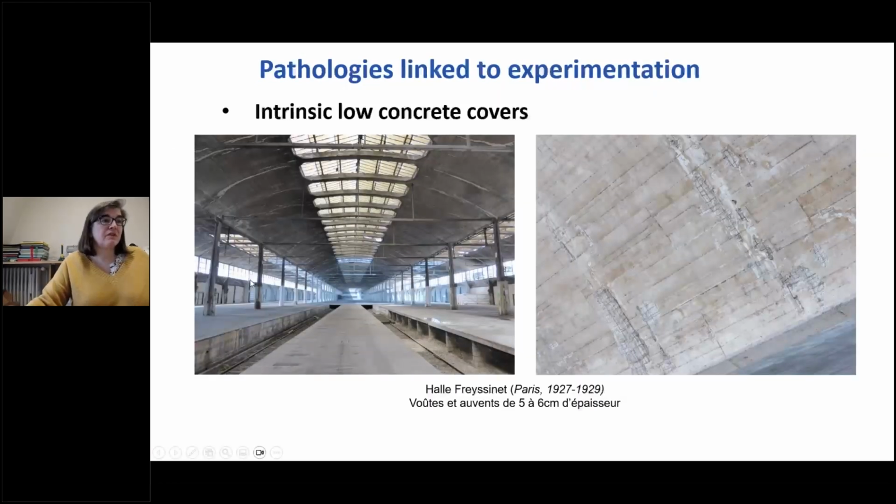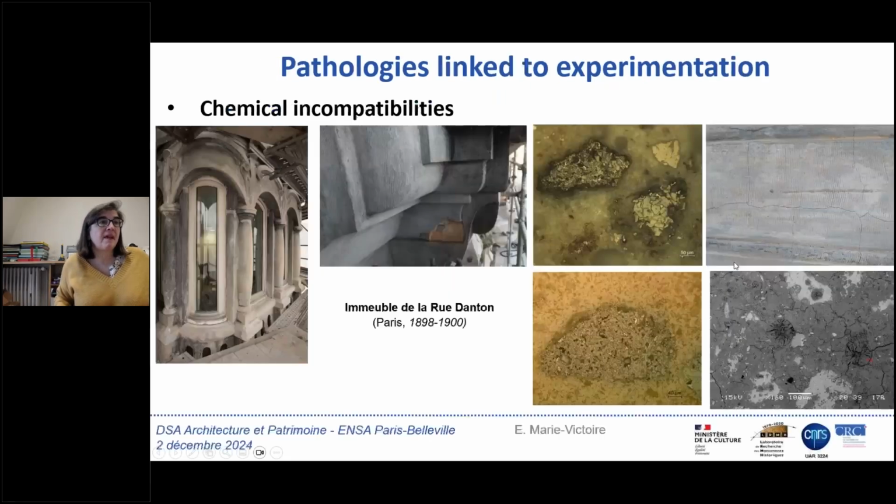And you've seen also Freycinet marketplace. This is another Freycinet place, and again the vault is 5 to 6 centimeters thick, so that the concrete cover is not enough, so that we have heavy corrosion.